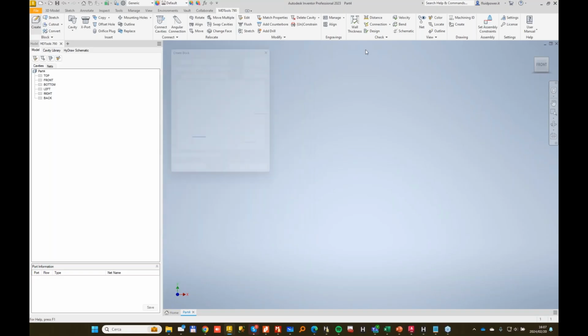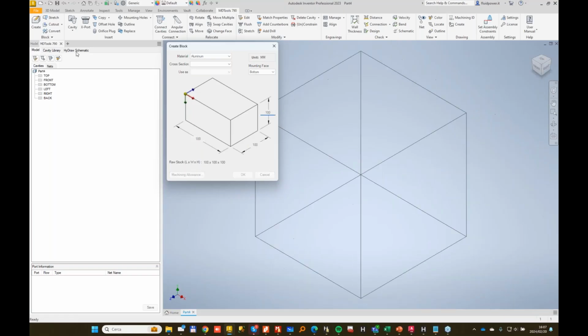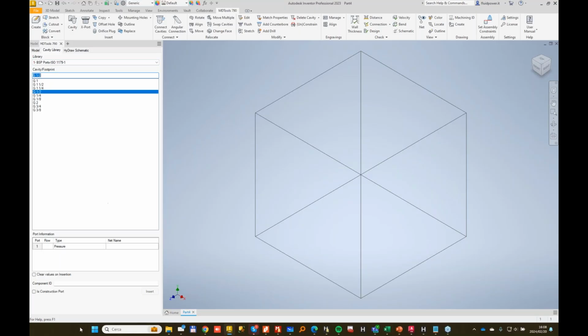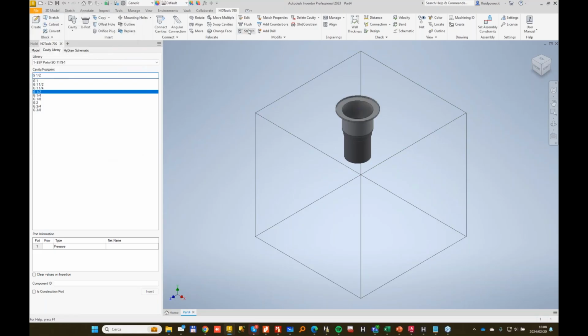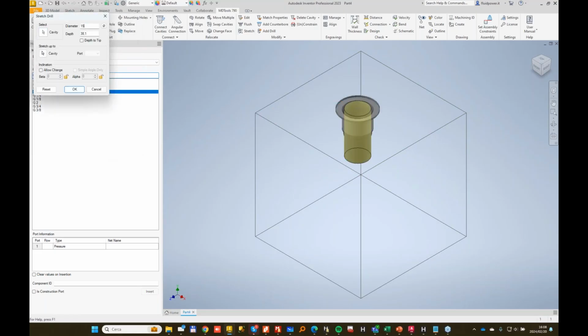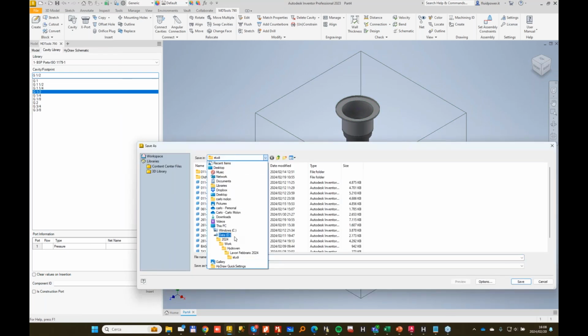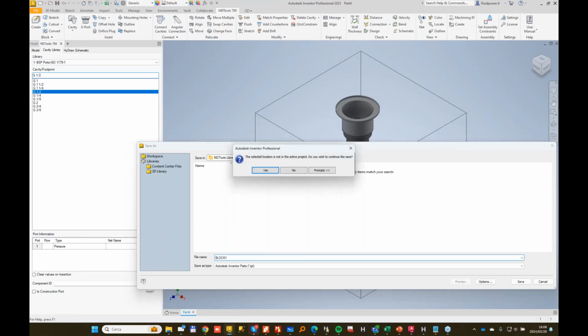So now if I create a new block, and we'll do some test with this block, and I put just a BSP port, just a 1x2 BSP port, and I call it port number P, and insert in the drawing. And maybe in my drawing, I change this diameter to 50. And let me save it somewhere into my block. And let me put it into my webinar February. And I call it block 1.